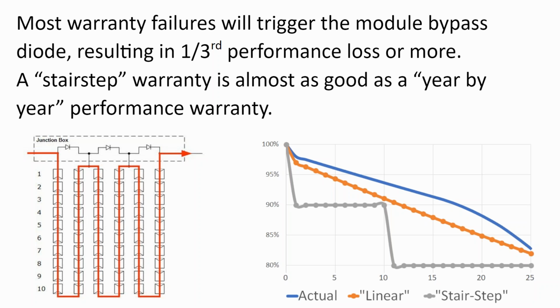And sometimes the cracks in the cells don't matter, like we saw with the snail trails earlier, and the panel will keep working. Other times it'll result in the connection being completely destroyed, and that typically results in 1/3 of the voltage dropping out of the panel. So, just because you can put weight on the solar panel itself, you should always try and put the weight on the actual frame and not on the surface of the glass.